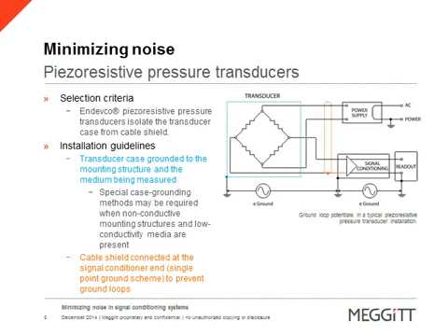Though the signal ground is isolated, there may be some special applications for high potentials that could cause a problem when the sensor is actually grounded to your media or your grounding surface, and since the shield is not connected, then there could be some difficulty with this high potential causing problems with your signal. So you must be aware of it and take precautions as necessary.